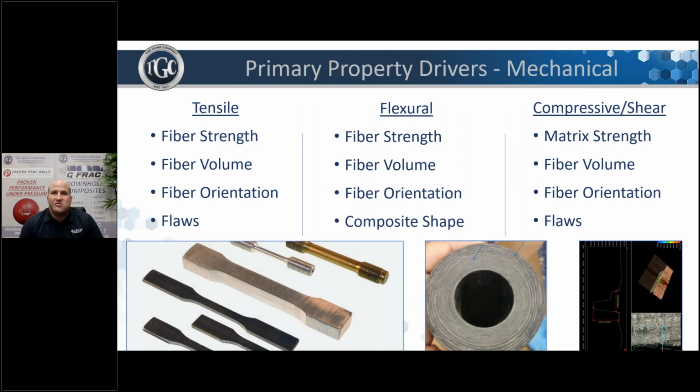We know most of the applications you work with, you're interested in the mechanical and physical properties. Mechanical properties are highly influenced by the fiber content and the fiber orientation. Tensile is mostly driven by fiber, while compressive and shear are primarily affected by the matrix. Flexural, since it is a combination of tensile and compressive, can be affected by both fiber and matrix.